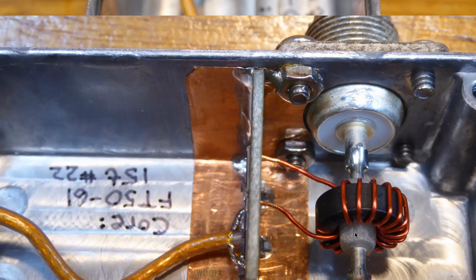Teflon will have a dielectric constant of 2.1. I use polyethylene a lot of times, high-density polyethylene, because it's available. It's really cheap. And it's got a dielectric constant of 2.2. So does polypropylene. But if we go to other materials, like this is a glass material, it's got a dielectric constant like 2.6. If we go to the common plastics like PVC, ABS, they're generally around 3.5. All these things increase the capacitance from here to these windings, which makes solving the problem a little more difficult.